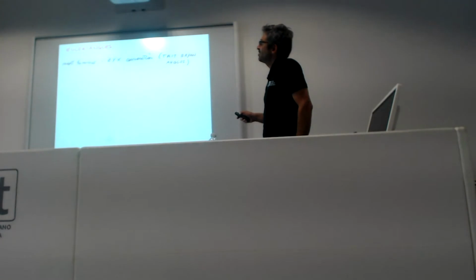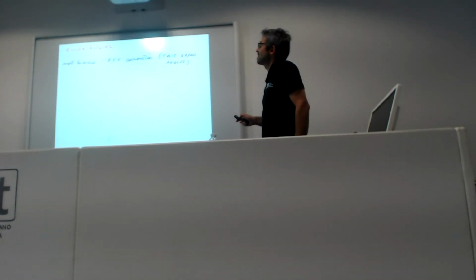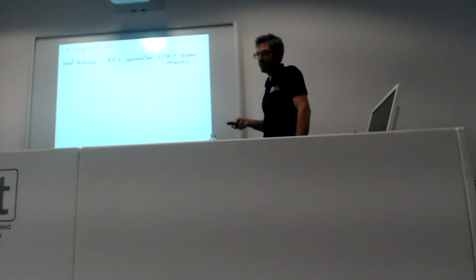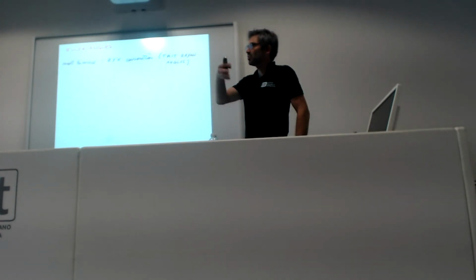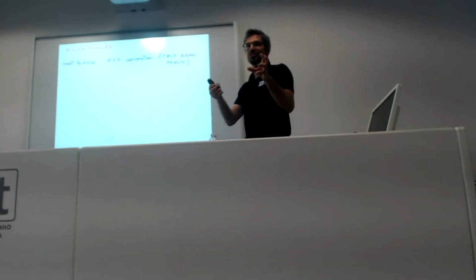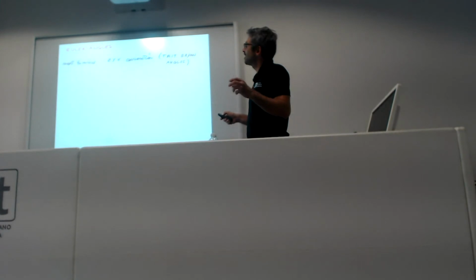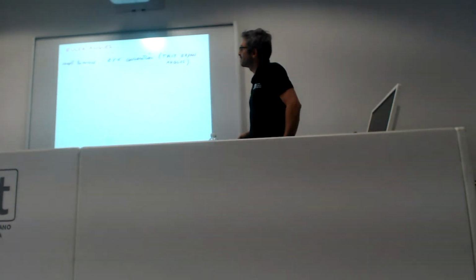And the convention that people use most is the ZYX. To get the orientation of a frame, we do 3 rotations. One about the Z, then about the Y, then about the X.